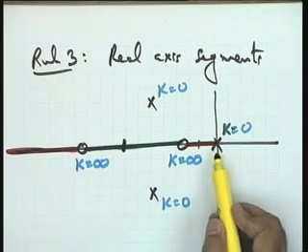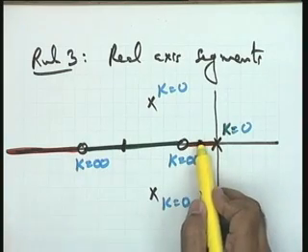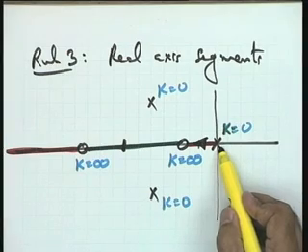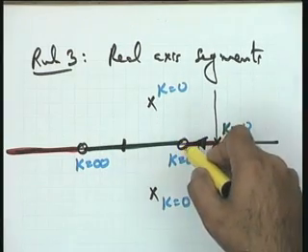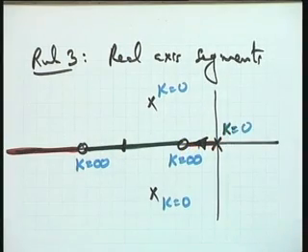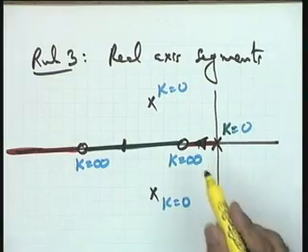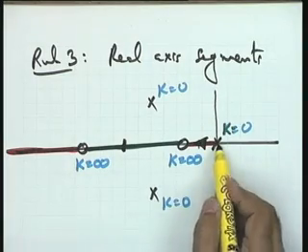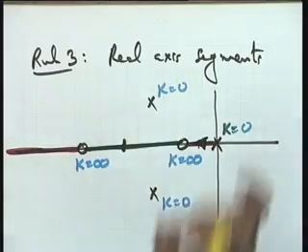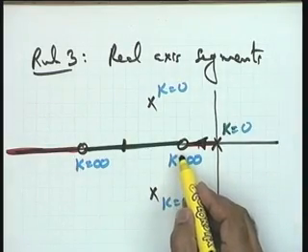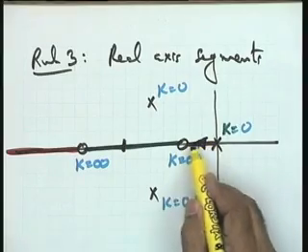It appears as if one of the root locus branches is just complete, because you are starting from k equal to 0 and going to k equal to infinity. Well, you have to prove it, but by other rules it will become very clear. At this juncture I may tell you that this gives you a complete root locus branch, because a starting point and a terminal point have been obtained, and this entire thing lies on the root locus.